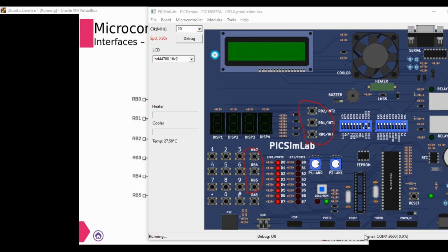Can we go for RC debounce externally? However you want to take care of it, you can do it. It is not that this is the only way, but because we are programming an embedded system, it is easy to take care of it internally in the software in your program.